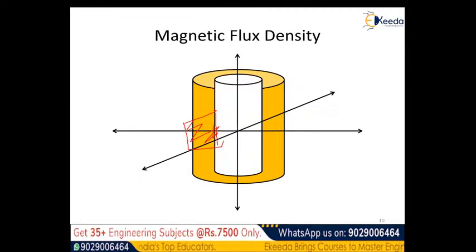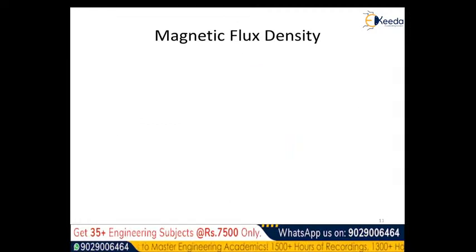and through this plane how much magnetic flux will be crossing, that we have to compute, and that will be the solution to the question here. So now let us solve part A, where rho is ranging from 0 to 1.2 centimeter. Rho is greater than 0 but less than 1.2 centimeter. First of all, to determine the total amount of magnetic flux crossing the plane as defined, we need to find capital J, the cross sectional current density. Then using capital J we can compute capital H, the magnetic field intensity, and then using the magnetic field intensity we can compute the magnetic flux density, and integrating it will give the total magnetic flux.